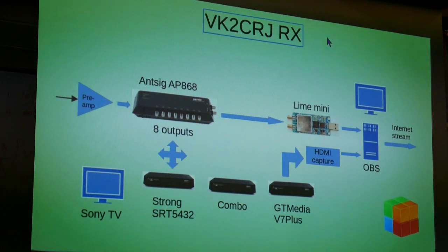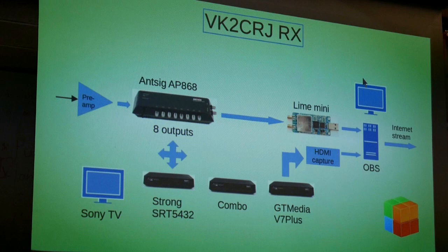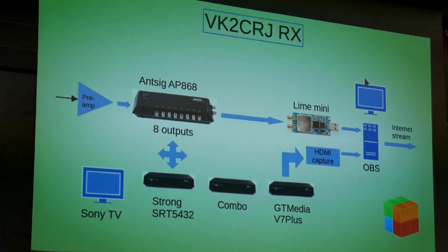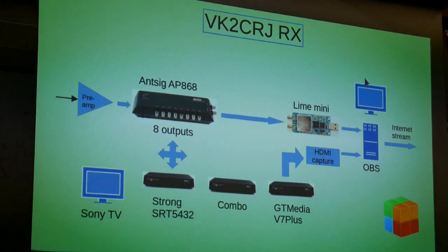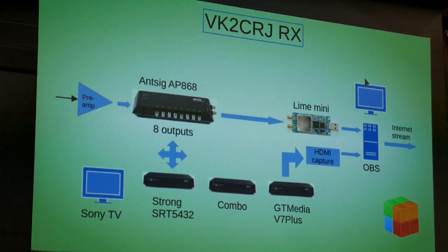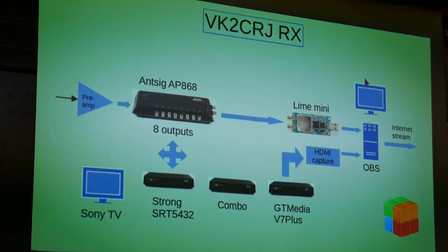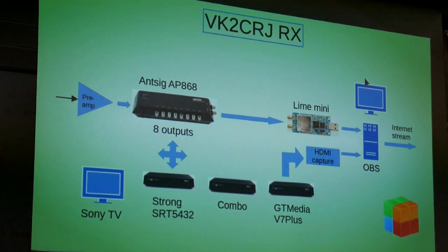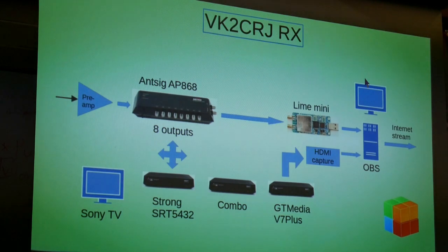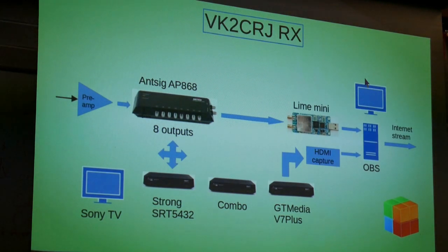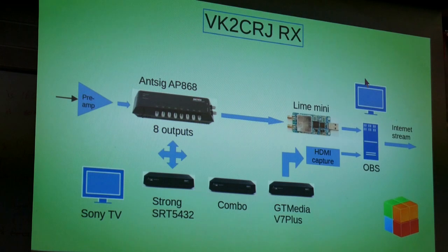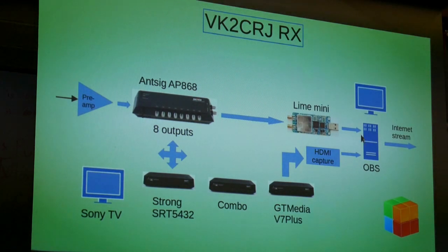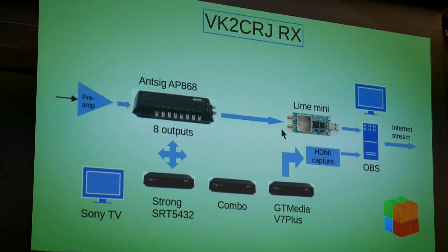But his DVB-S decoder doesn't work as well as the NIM module. I've done a comparison of those two together, and it needs 5 or 6 dB more signal for that software decoder to work. So he's probably taken some shortcuts in his decoder. He hasn't done his error correction as well as he could have done. He could take some shortcuts there to cut down CPU effort. I don't know, but in theory it should work just as well, but it doesn't.